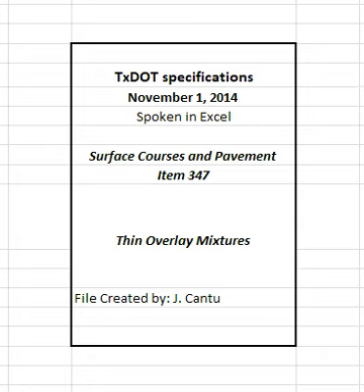content established for JMF1. However, mixture produced using JMF2 must meet the voids in mineral aggregates, VMA, requirements for production shown in Table 6. If the optimum asphalt binder content for JMF2 is more than 0.5% lower than the optimum asphalt binder content for JMF1, the engineer may perform, or require the contractor to perform, Tex-226-F on Lot 1 production to confirm the indirect tensile strength does not exceed 200 psi and the overlay test exceeds 300 cycles.